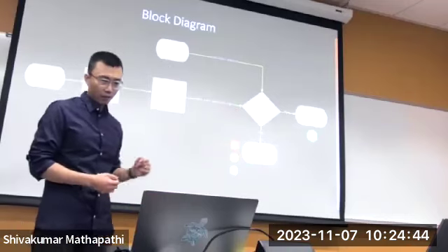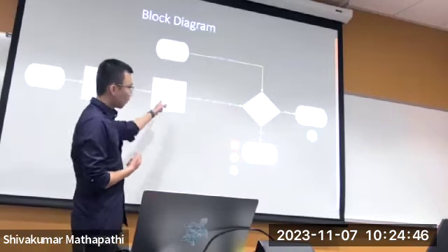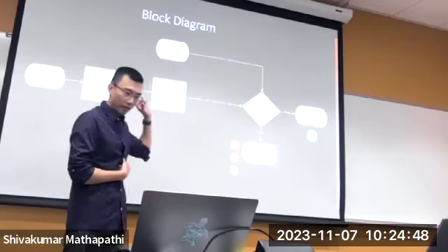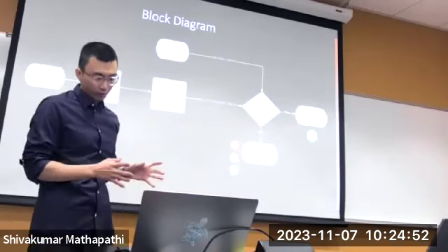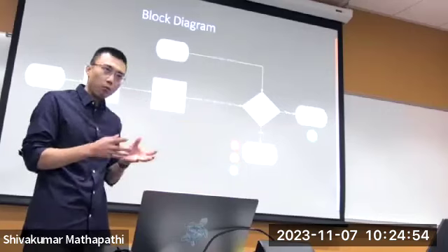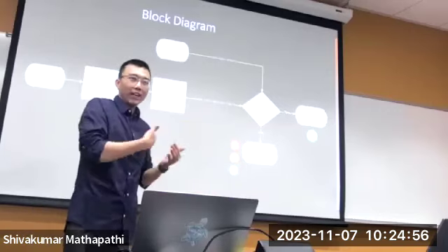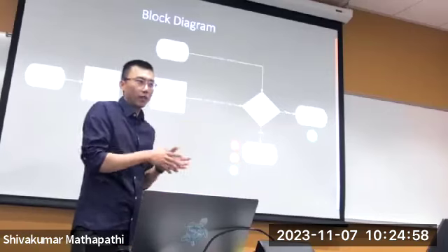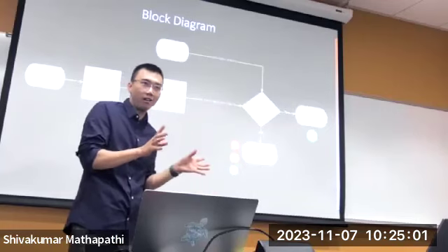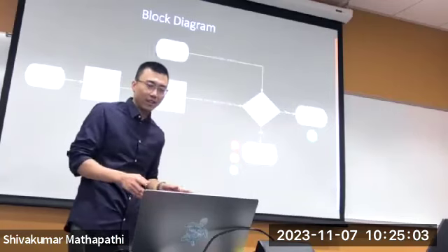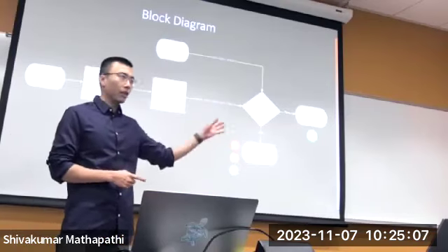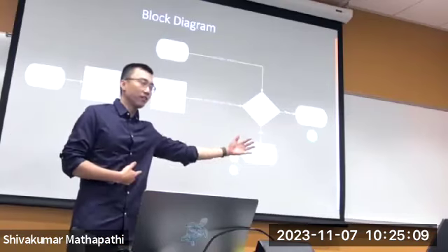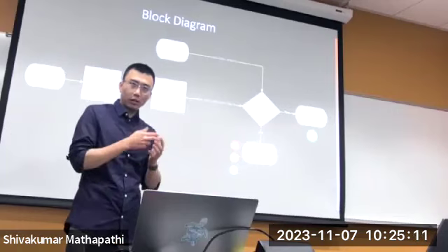Okay, now we have the detected result, and we also have the distance information for the other direction. So we can just use a loop to iterate over each detected object to see if that object is a car. If it's a car-like object, and the ultrasonic sensor distance is larger than a certain value, so it's clear, are these two conditions met?